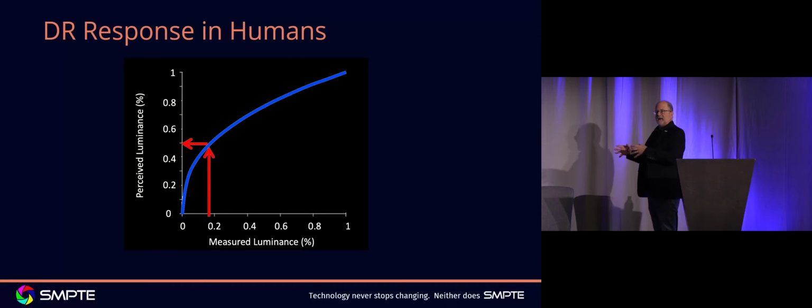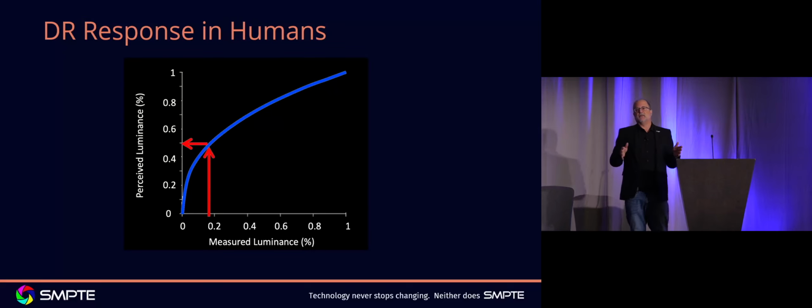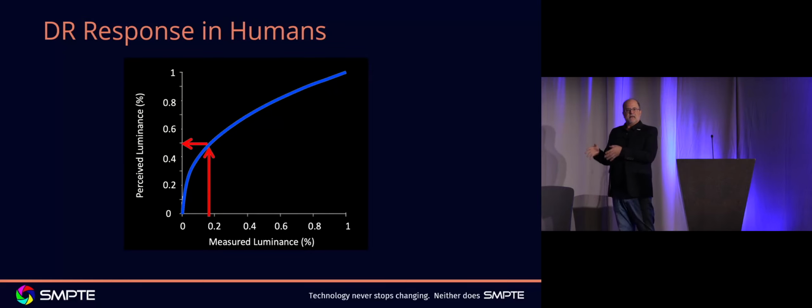So in a display world, we're going to use 10 bits. So 2 to the power of 10, so 1,024 levels. That's enough to represent a high dynamic range image on a display. You're going to capture at a higher bit depth than that because you want to have some freedom in post-production to play with the levels, bring the light down without artifacts, push some things up. But for the display side of things, 10-bit is enough for high dynamic range.